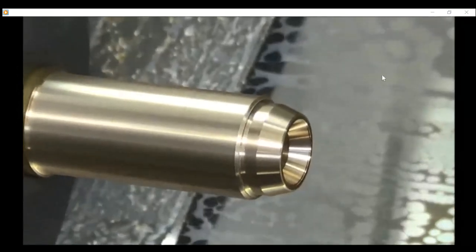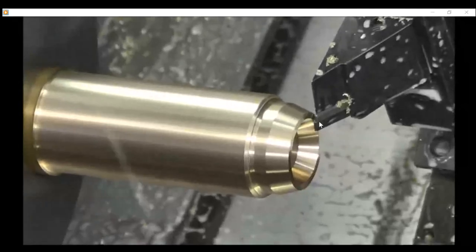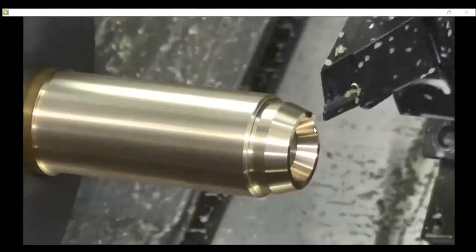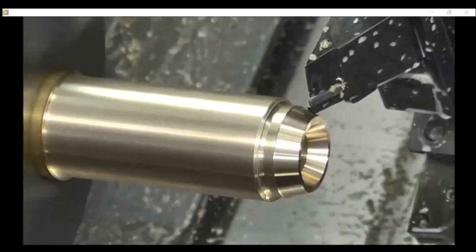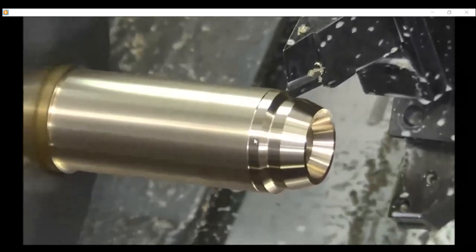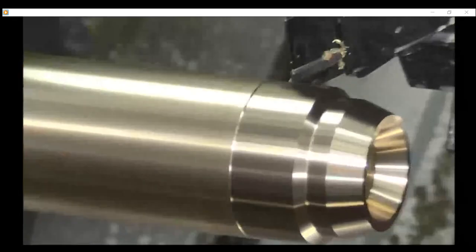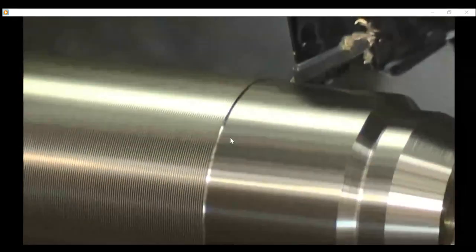And now another tool, this is the tool for finishing. This is finishing. I hope you realize this is the depth of cut. Can you see that? I'll stop the video. Depth of cut here is smaller. And can you see the difference? Quality here is low quality. Quality here is better, excellent quality.